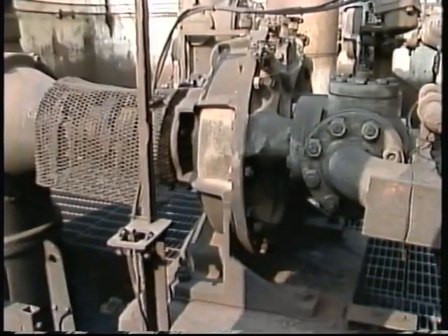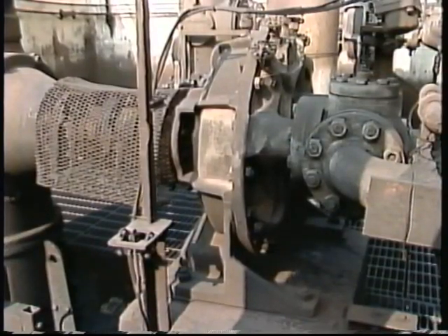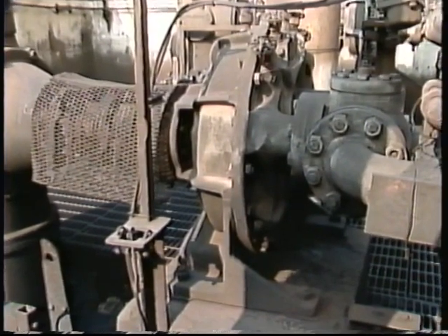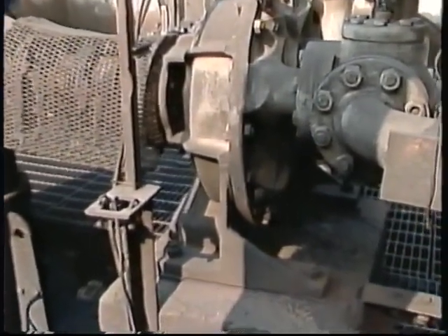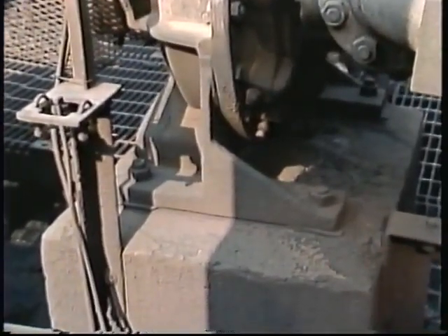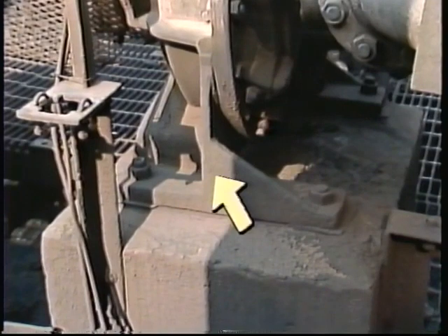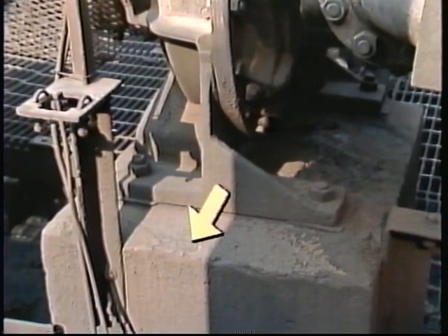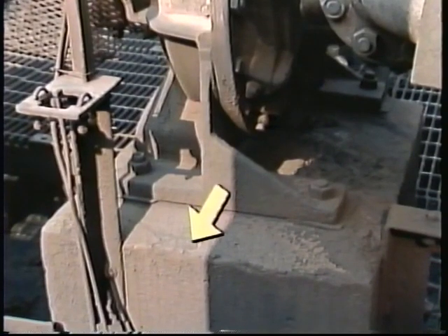During operation, the turbine must be stabilized so the rotor doesn't move out of its properly aligned position. Bearings, as we've already discussed, help position the rotor. In addition, a pedestal supports the turbine. Mounting the casing on a concrete foundation provides stability, too.